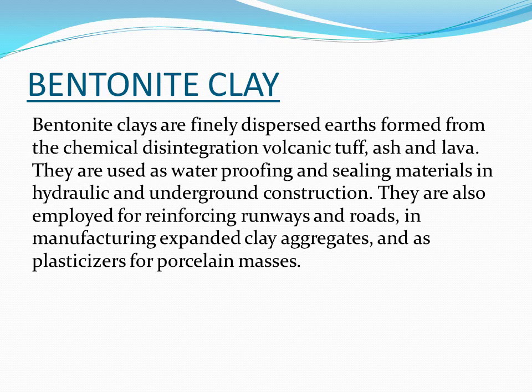Next is bentonite clay. Bentonite clays are finely dispersed earths formed from chemical disintegration of volcanic tuff, ash, and lava. They are used as waterproofing and sealing materials in hydraulic and underground construction. They are also employed for reinforcing runways and roads, in manufacturing expanded clay aggregates, and as plasticizers for porcelain vases.